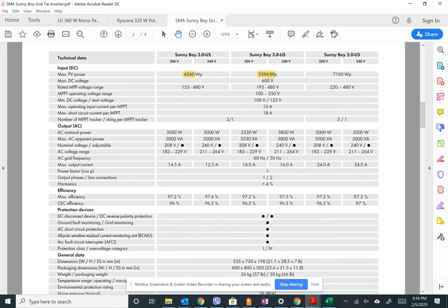That's fine because remember that we used VOC. You're probably never going to see that VOC. Actually, you won't because VOC is more of a theoretical value. Remember, if you have your VOC value, you have zero current based on our IV curves. And if you have zero current, that means you have zero power, right? So you're not going to see VOC.